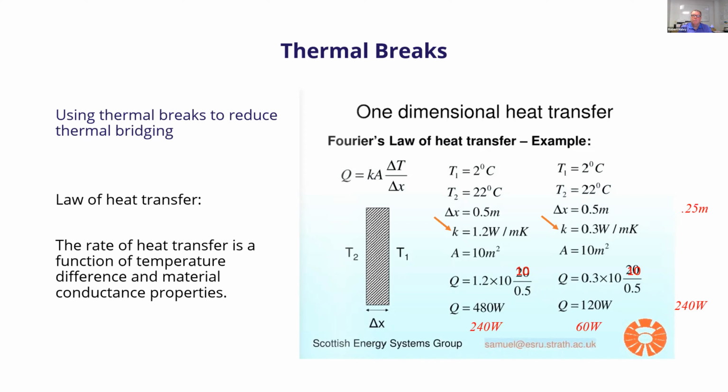That makes sense. So it's not rocket science, but there is some physics involved here with the first law of thermodynamics. And you just need to be cognizant when you're working with thermal breaks of what am I working with here for thermal conductivity, and what is the heat flow actually going to be coming through this material? Am I making things worse or making things better? It's often overlooked, and I see so many details where these materials are very thin, and I think the concept is, oh, I've made a physical break, so I've reduced the heat coming out, but that's not always the case. So just be careful of that.